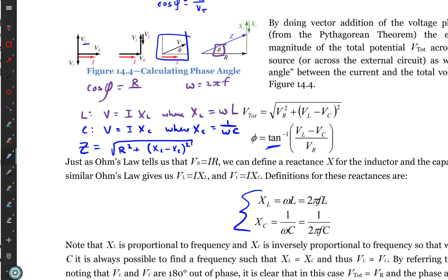That means the inductor is not perfect. It's not going to behave like it has zero resistance. It's going to behave like it has a real resistance. So in our analysis, we're going to have to take into account that the inductor is behaving like an ideal inductor with no resistance, plus a resistive portion. And so we're going to have to find that resistive portion in our work.